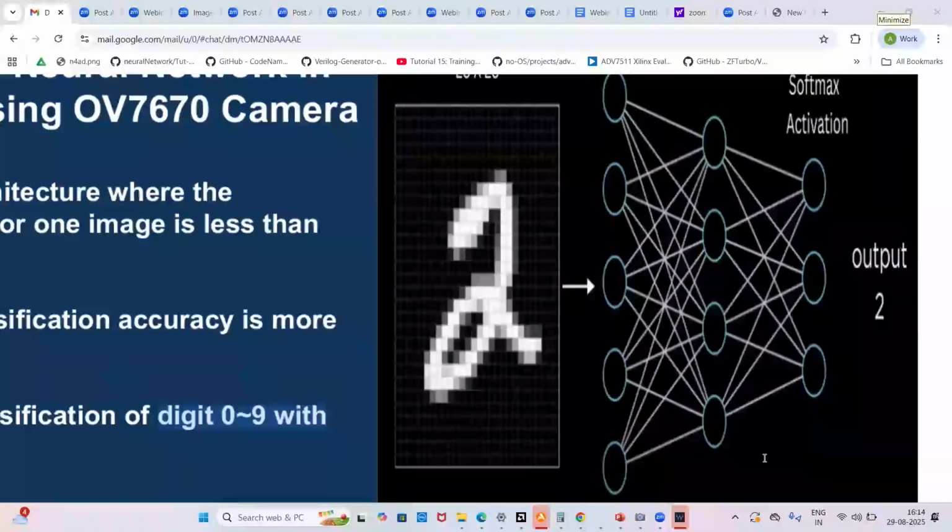You have to use certain Python functions. Like I told, Vitis HLS is going to give you OpenCV libraries, which are included in that. It is not something that is controlled by Vivado. It is something which is generated. Those custom IPs are generated from Vitis HLS, and you are importing those Vitis HLS IPs in your RTL design. Based on those OpenCV libraries, you have taken those trained data values, and you are just integrating that IP to your output format to integrate the visual processing unit.